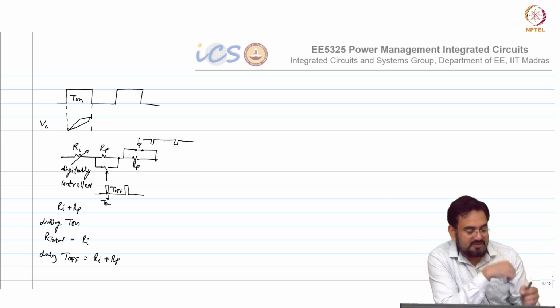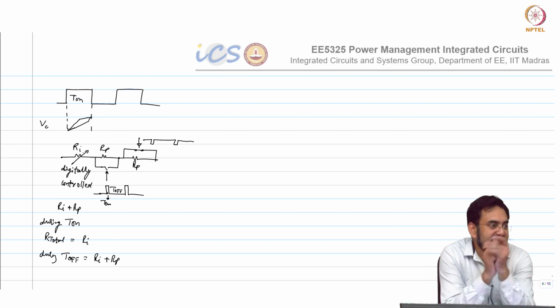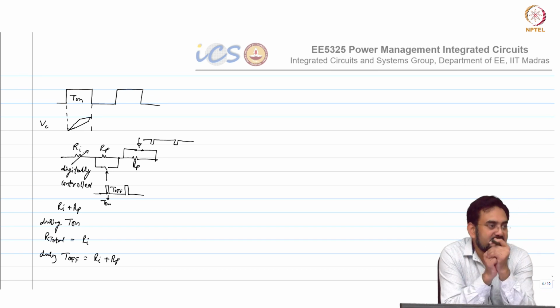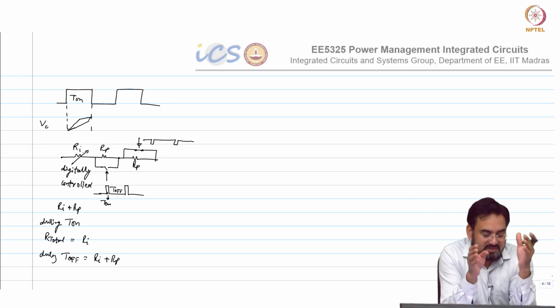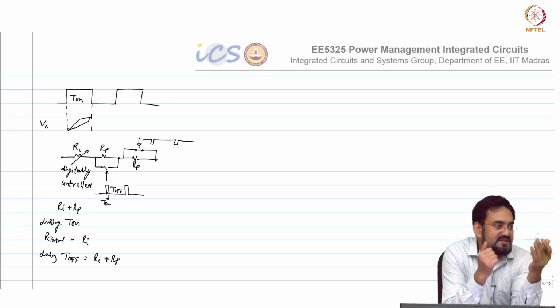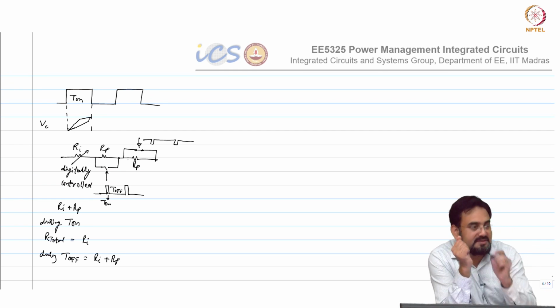Okay. So your coarse control is already frozen. Let us say now I am left with the 3% error, which is coming due to the finite resolution of that DAC I have. So I want to correct that 3%. So these up and down pulses will be generated based on whether it is plus 3% or minus 3%, and that will control this.